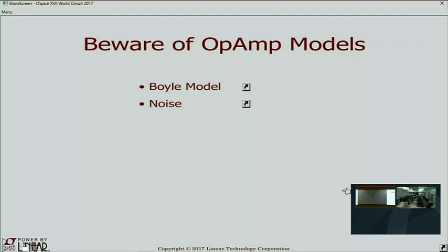And the real reason why it doesn't work is that SPICE is an incredibly bad programming language to describe op-amp behavior. I mean, it does pretty good with transistors, but the person who made the op-amp went through great lengths so that you don't see transistor behavior in this op-amp. You just see idealized or nearly idealized behavior. And SPICE is a really bad programming language for describing that almost ideal op-amp behavior.